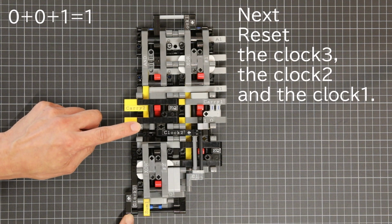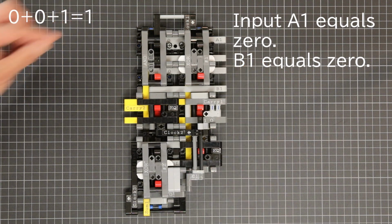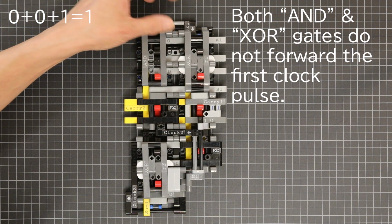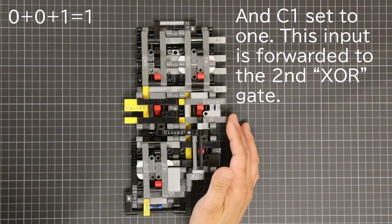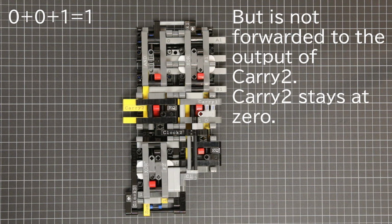Next, reset clock 3, clock 2, and clock 1. Input A1 equals 0. Input B1 equals 0. Both the AND and XOR gates do not forward the first clock pulse, and C1 is set to 1. This input is forwarded to the second XOR gate, but it's not forwarded to the output of carry 2. Carry 2 stays at 0.